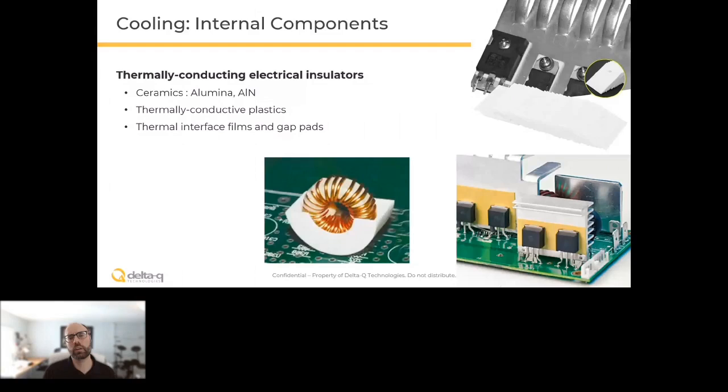That can be put in place with through-hole devices, as is seen here. Typically, it wouldn't be screwed together like this because that might violate the isolation which is needed. So there would probably be clamping systems, but ceramics are a good tool here, and they can be quite low cost. The main issue being that ceramics have quite a hard surface, so typically thermal grease or some sort of a thermal interface material or paste is needed in that joint.